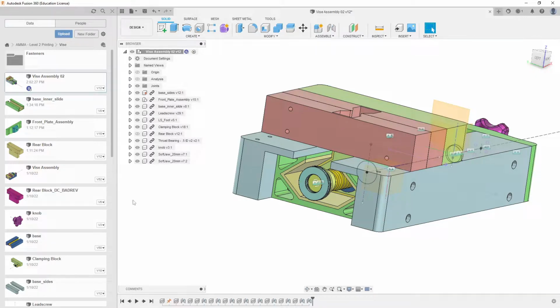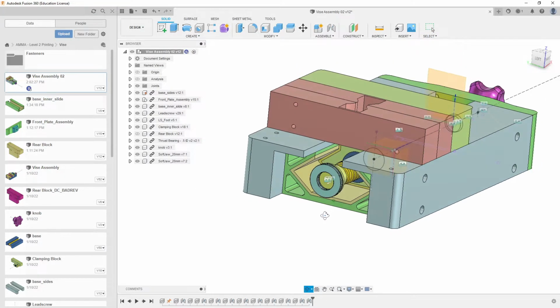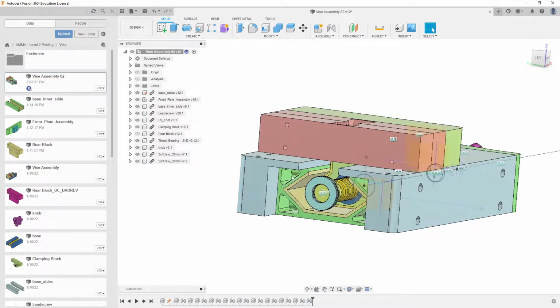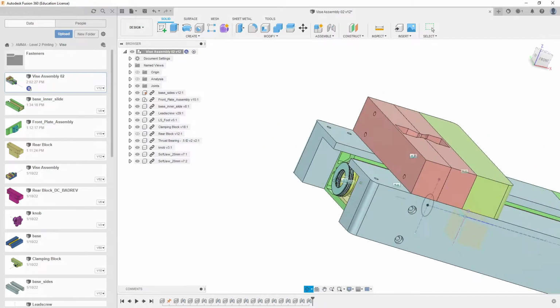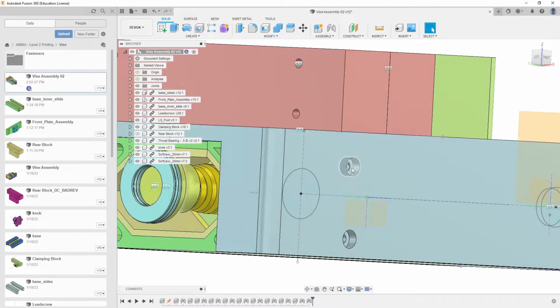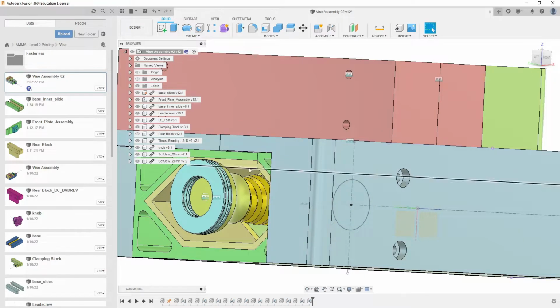So I'll talk about that, and then after you get everything divided up into these separate lumps, you have to assemble them at some point. And if we say things like glue is not allowed, because if this was metal, something we did on a CNC, you're not necessarily going to glue those together. We have to have fastener holes. So, for example, again on the side here, we've got holes that go through into this green shell of the inner sleeve area there. So that makes entirely good sense.